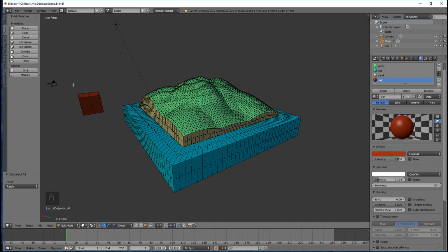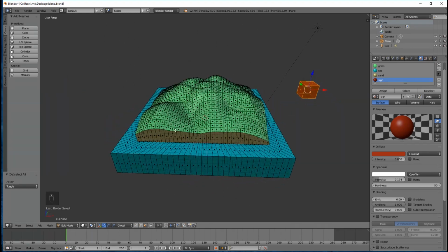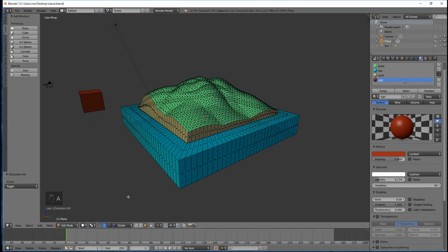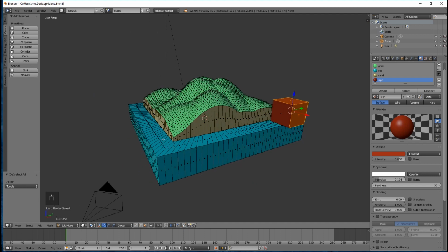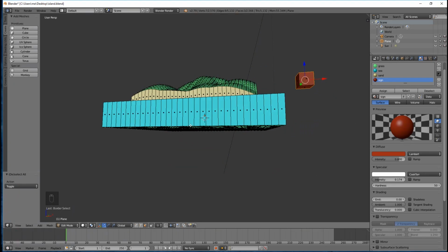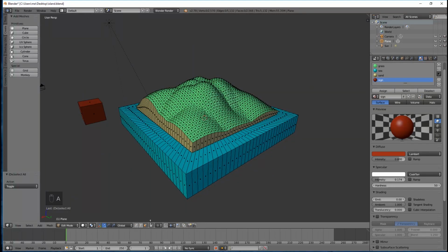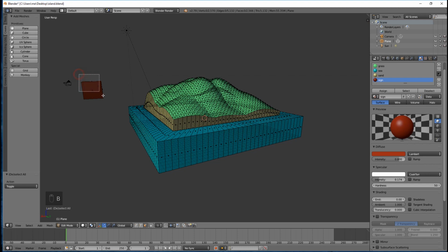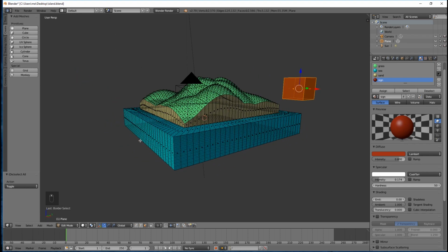The second thing is to press the letter B. B for crosshairs. B for, I don't know, B for something. And with these crosshairs, I can click and drag a frame over everything I want to select. And you see there I've selected the whole of that little cube, including the opposite sides. Let me show you what would happen if I didn't have that transparency on. So there's transparency on, there it is off. If I use the B now and I select that cube, it looks as though it's all selected, but if we look at the back, you can see that the opposite faces weren't included. So in order to make sure that when I use those crosshairs, everything inside that frame is selected, I need the transparency to be on.